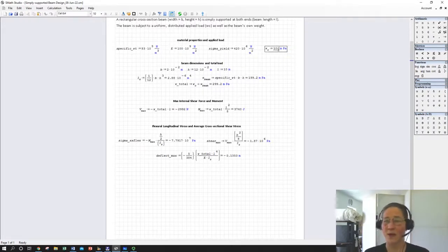Do we care about how much we can hold up? Presumably we are putting this beam into place to hold something up. So this one value here represents the entire purpose of the design, if you want to think about it. And you would presumably want as much of this as possible for as little material total, and also as little material weight as you can get, because that material weight, of course, adds to the carbon footprint of manufacturing, bringing to site, and possibly even end of life disposition.